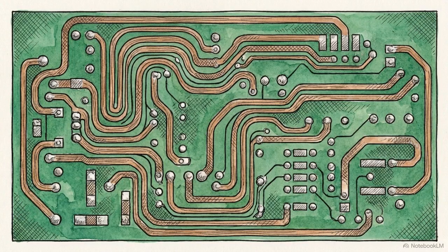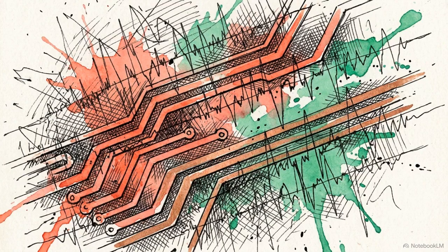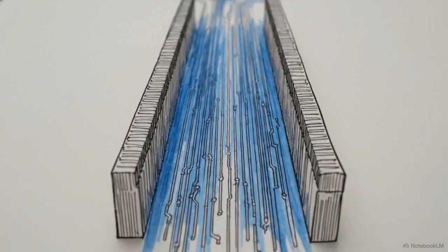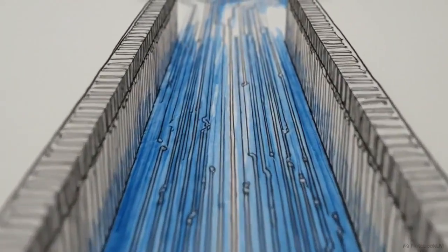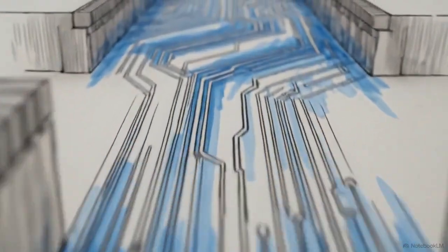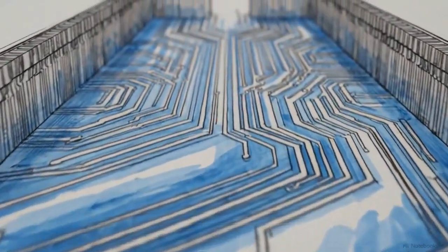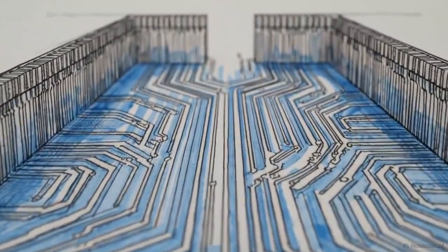A standard interconnect traversing a motherboard often needs to push signals across 100 millimeters or more of copper trace. At those lengths, a printed circuit board is a hostile electrical environment, highly susceptible to insertion loss and crosstalk interference from neighboring components. However, inside an advanced package, the physical distance between two separate chiplets shrinks down to a microscopic gap of less than 2 millimeters.